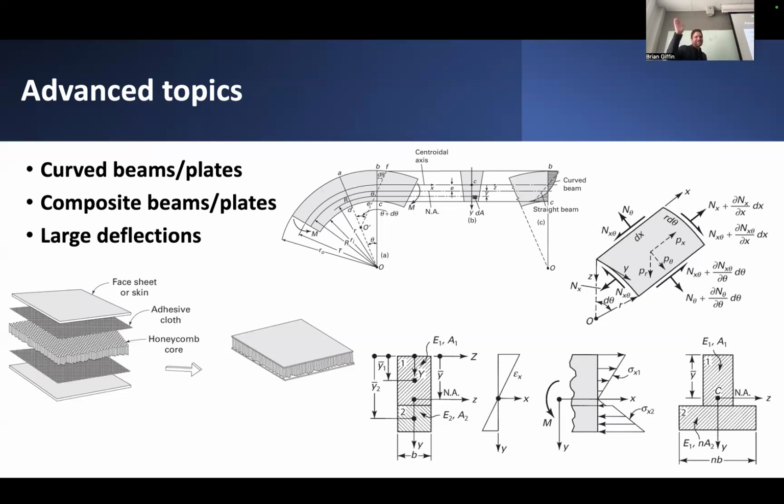It's really worth mentioning that they're interesting subjects, but oftentimes when you try to represent these things in a finite element analysis code, you can only really do it approximately. Most of the time, the types of beams and shells that they include in their analysis frameworks don't actually include that initial curvature. So to represent the geometry, you have to approximate it in a piecewise linear, segmented way.